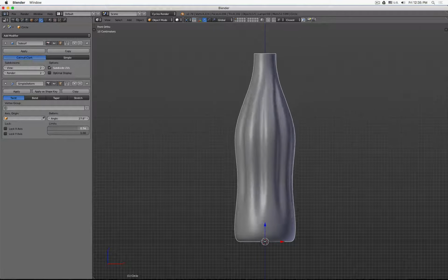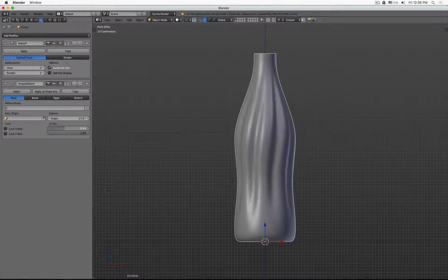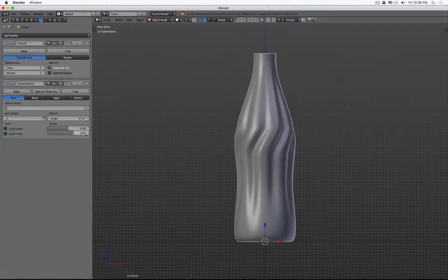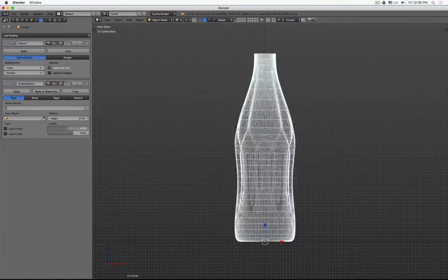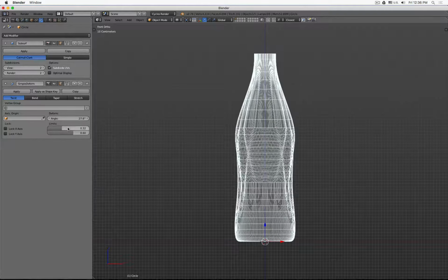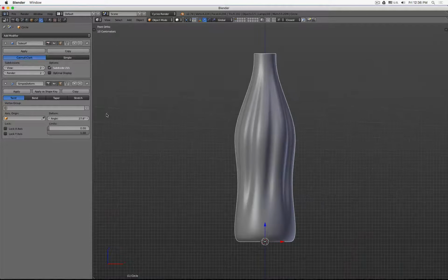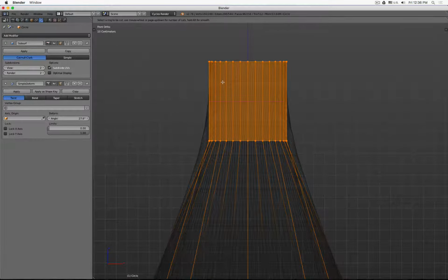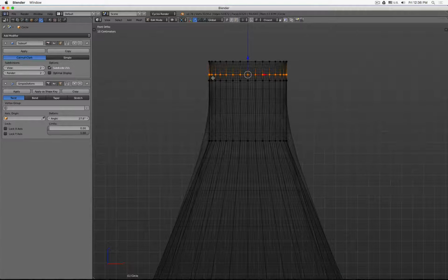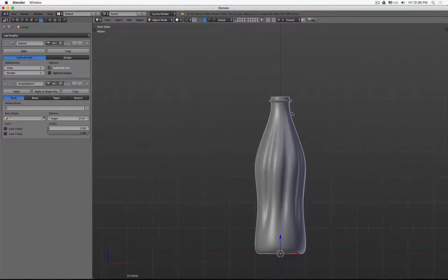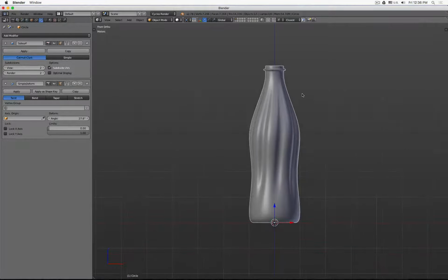There's also a slider where we can, for example, adjust how much or what type of limits we have. So you see it only twists in the center a little bit. So now we are twisting the whole object. I'm going to make one there, select all those, E, escape, S, Shift Z, Control R, let's move this one up, and there we have a small lid, ding. Okay, so that was a twist one.